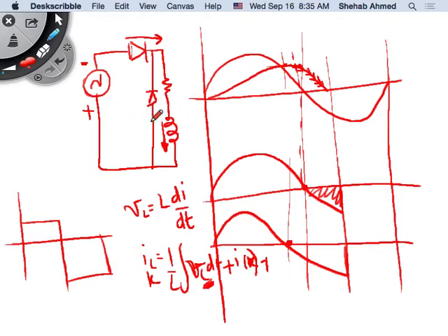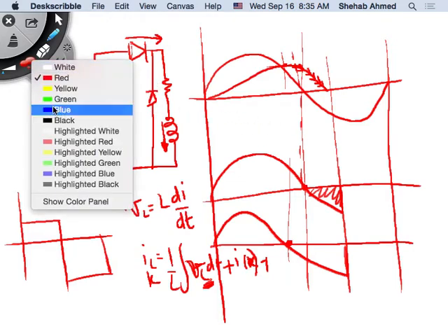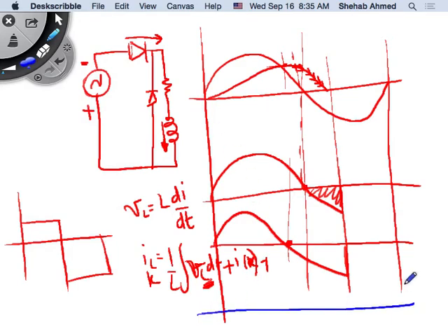So when I put the freewheeling diode, what happened? What happened to the output voltage when I put the freewheeling diode? This was the output voltage without the freewheeling diode. Current was flowing this way, right? Now it has this path, which is a nice, easy path to flow through, or it has this tortuous path, because it's a voltage that's pushing the current in the opposite direction. So which path will it flow through? The easiest path. Exactly. So it will flow through this path.